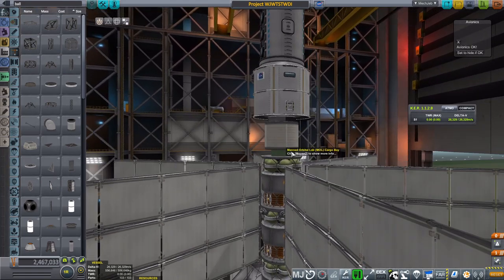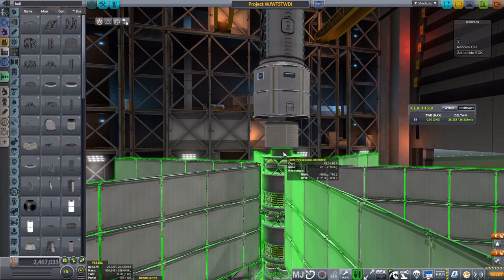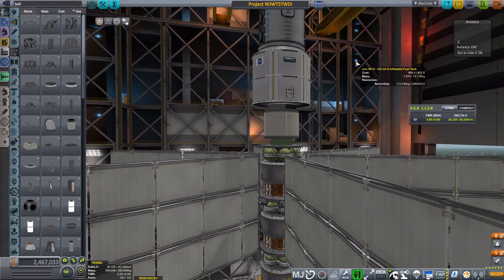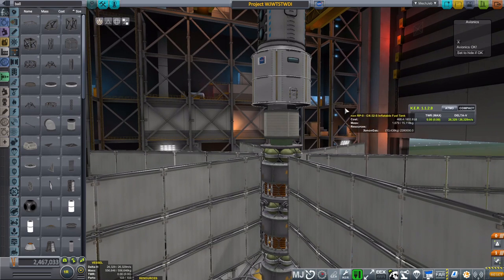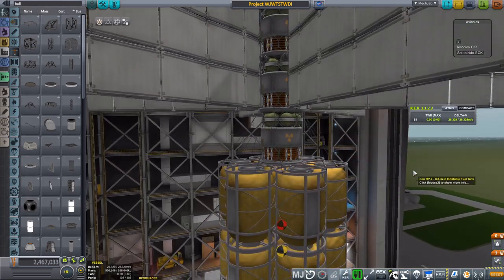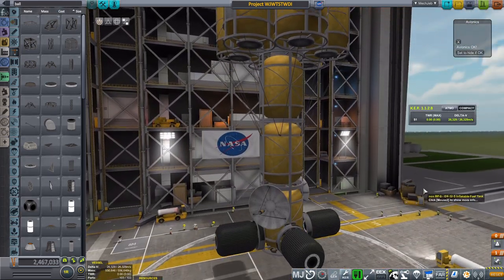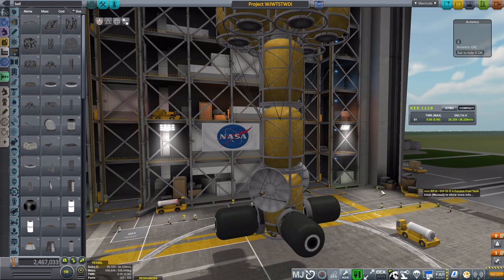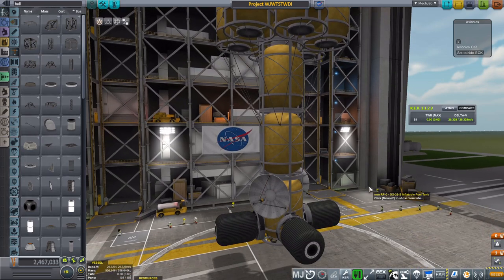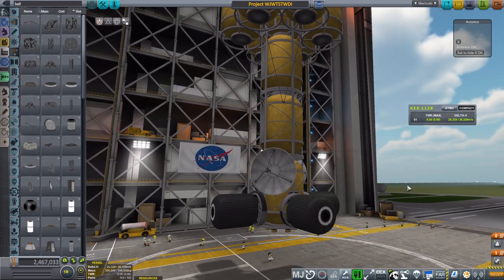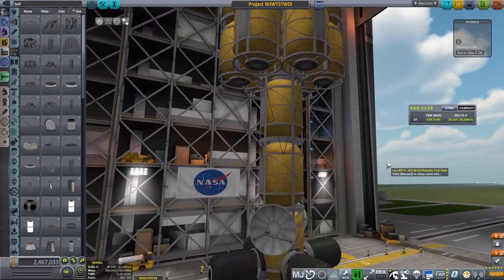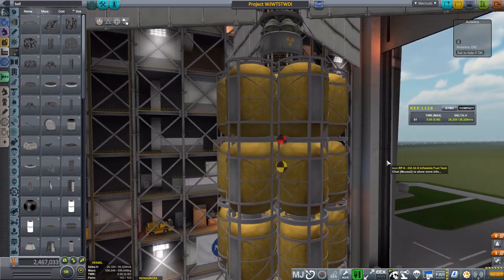So continuing on, that's a small tank meant to represent the mass of RCS systems, or reaction control systems. So the reaction wheels here, I put about 5 of them on board. They use very rapidly spinning disks to reorient the craft without using any fuel, but those can become saturated, where essentially the wheels are spinning so fast that you can't spin them up any further, or you have to de-spin them in order to allow them to continue to work.